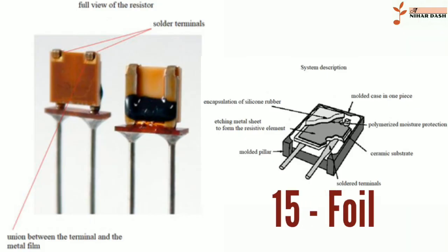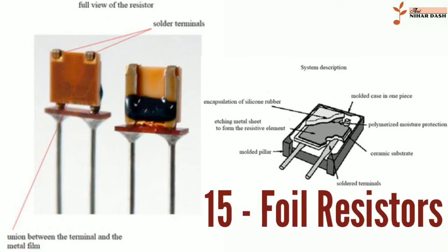15. Foil resistor. Metal foil resistor. In 1960, Felix Zandman and Sidney J. Stein presented a development of resistor film of very high stability. The primary resistance element of a foil resistor is a chromium nickel alloy foil, several micrometers thick. Chromium nickel alloys are characterized by having a large electrical resistance, about 58 times that of copper, a small temperature coefficient, and high resistance to oxidation.